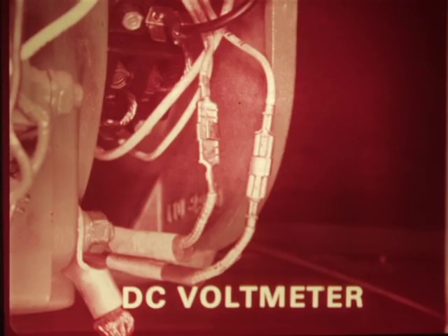Now, if the engine is tuned properly, it should be able to pull a load without a big drop in output. So if engine RPM doesn't drop much, but voltage output does, there's a good possibility that the compounding reactor is bad. To test the reactor, lift the plastic flap and connect a DC voltmeter to the field leads. Clip the positive lead to the F1 wire terminal and the negative lead to F2.